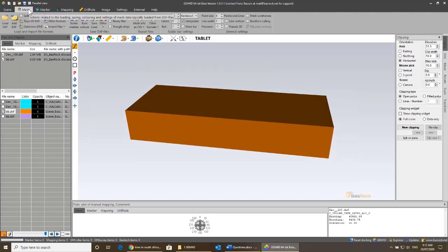If you go to the ribbon, go to mesh, and you go all the way to the general settings, there's one checkbox that says backface culling. Now, if you check the backface culling box, so I now check, and nothing changes within your scene, that means that all the polygons are actually looking to your side.